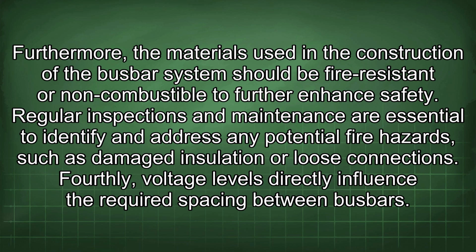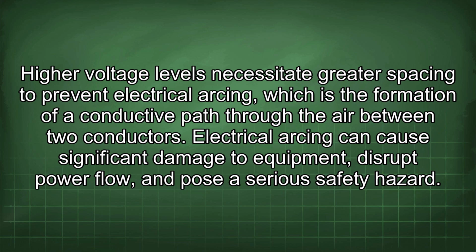Furthermore, the materials used in the construction of the busbar system should be fire-resistant or non-combustible to further enhance safety. Regular inspections and maintenance are essential to identify and address any potential fire hazards, such as damaged insulation or loose connections. Fourthly, voltage levels directly influence the required spacing between busbars. Higher voltage levels necessitate greater spacing to prevent electrical arcing, which is the formation of a conductive path through the air between two conductors.